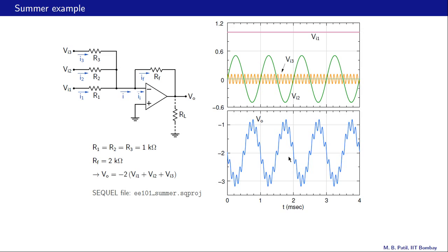And it is easy to see where this minus 2 volts is coming from. We have Vi1 equal to 1 volt, and that 1 volt gets multiplied by minus 2 here, and that gives us minus 2 volts. Alright, now let us make a few important points.